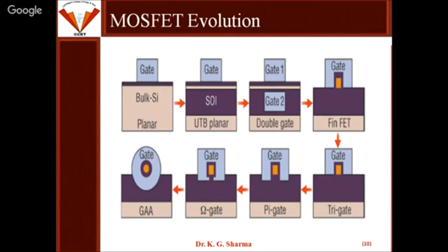Maybe if we can have some other technology by which we can reduce this parasitics, then obviously it will be a better choice. But compared with the tri-gate devices, gate all around is providing much more benefits. So at present, we can say that this is the better option, but we cannot say best because maybe in future we'll have better devices.